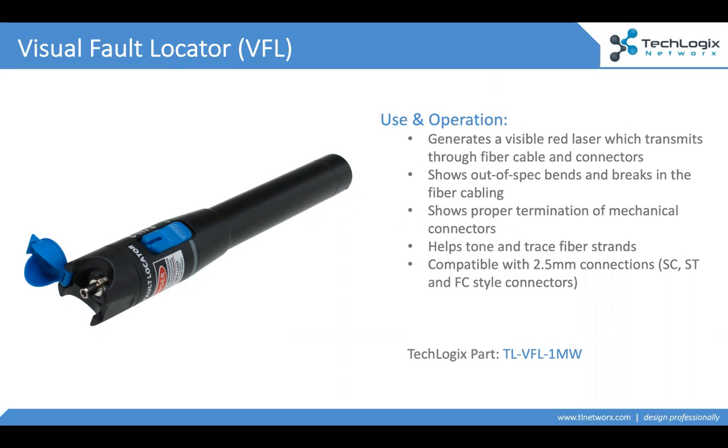Because when you find a lot of loss on a cable run or in an installation, the first place you go is those connectors. Typically, you'll find one connector that is not seated properly, and you're going to want to undo it and put it back on that cable. That solves a good majority of installation problems.